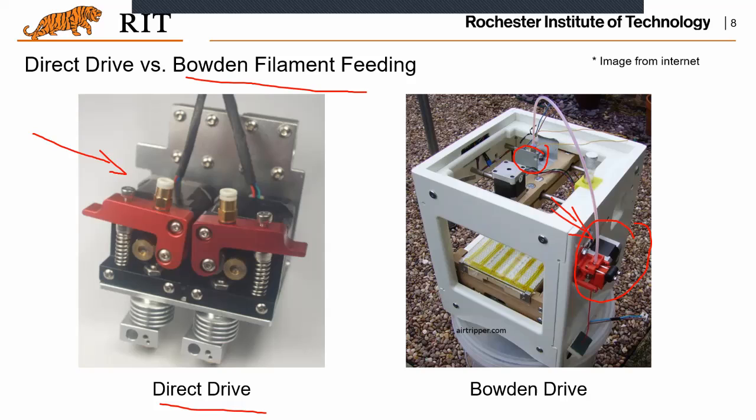And even with rigid material, there could be a jam because the distance between this and the hot end is very, very long. And in between, there are possibilities, for example, this has a problem or this has a problem, and it turns out it will spoil this printing together, right?